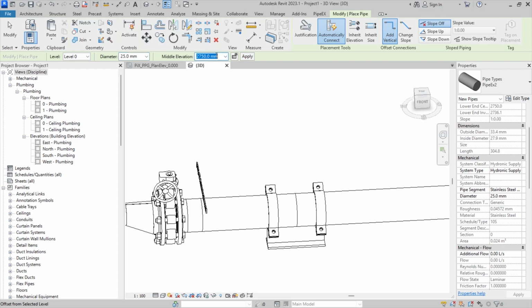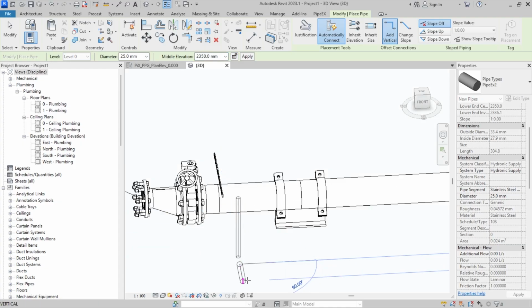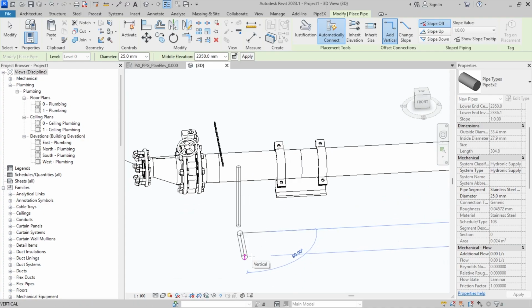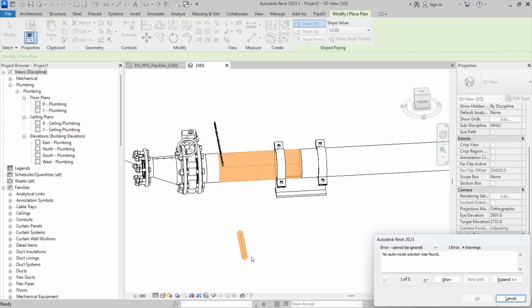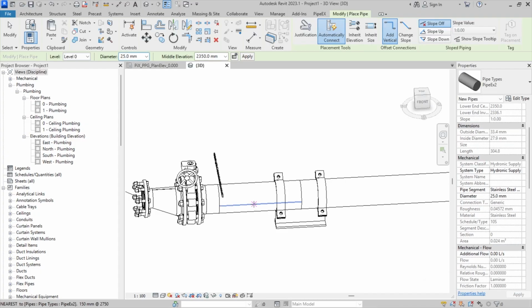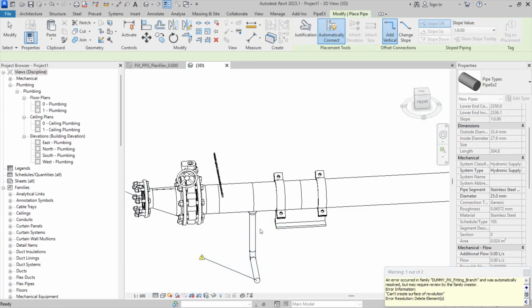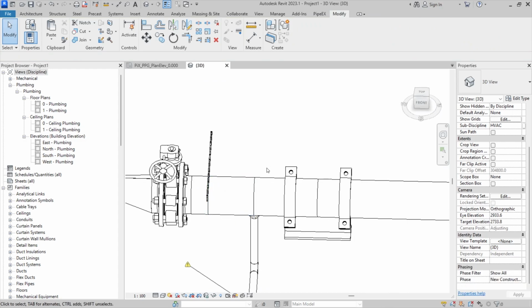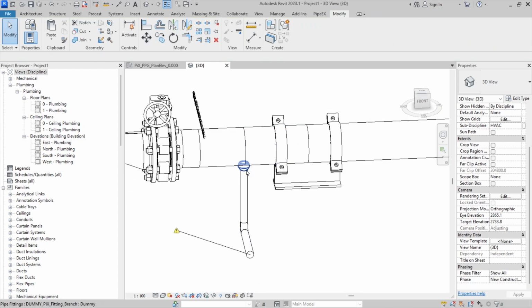and the elevation of it will be slightly lower than the center line of the pipe that we see right now. So let it be 400 millimeters lower, for example, 350. Straight pipe on plus minus this elevation, as you can see right now on the screen. Yeah, okay, I need to displace it for a bit, because by default in my case it started from the branch connection, and then it starts to adapt according to the lookup table.